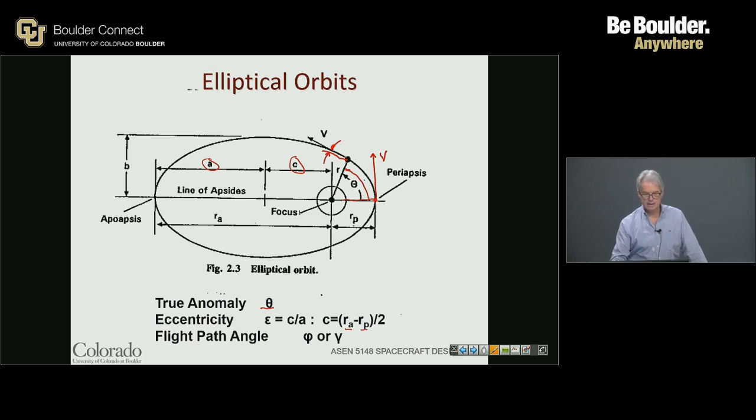Okay? Think of it as the spacecraft moving with relation to the body it's moving about, and that has a direction, but the velocity vector is pointed off that position. Follow the spacecraft through, and what you'll find is that the flight path angle essentially changes until it gets to apoapse, at which point, again, the velocity vector is tangent, meaning it's coincident with the direction of the spacecraft.